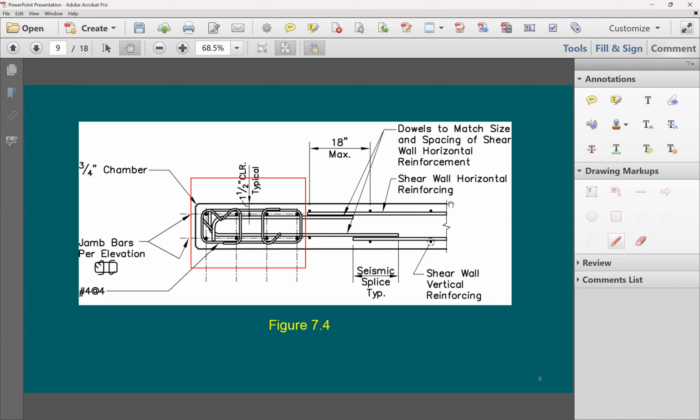Since I'm going to have a 16-inch thick wall, for sure I'm going to have 2 layers of reinforcing, not just one. If you remember, for the gravity walls and for all walls, if the wall thickness is greater than 10 inches, you need to put 2 layers. So in my case, I need to split this into the 2 faces or 2 sides. Actually what I need per face is half of this, the 0.48. As presented in this equation, it is going to be 0.24 square inch per side or per face.